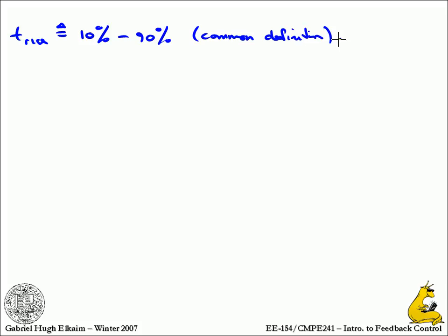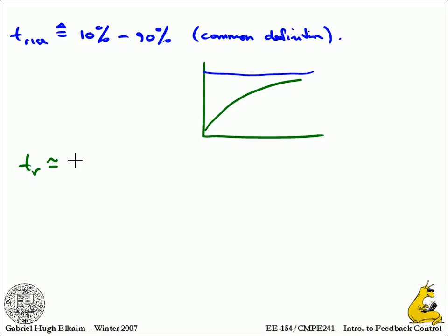All right. Here's another one. The rise time, and once again, this is defined from 10% to 90%. Why do they use 10 and 90? I don't know. It's the common definition. For circuits too. The reason is depending on whether you had overshoot or not. If you've got a very slow, critically damped system, it's asymptotic. So if you use 1, it's never there, right? So they just chose this as arbitrary. And if you do have overshoot, it's going to bounce around a little bit and may come below the 1. It doesn't work either. So for here, again, this is approximately 1.8 divided by omega n.